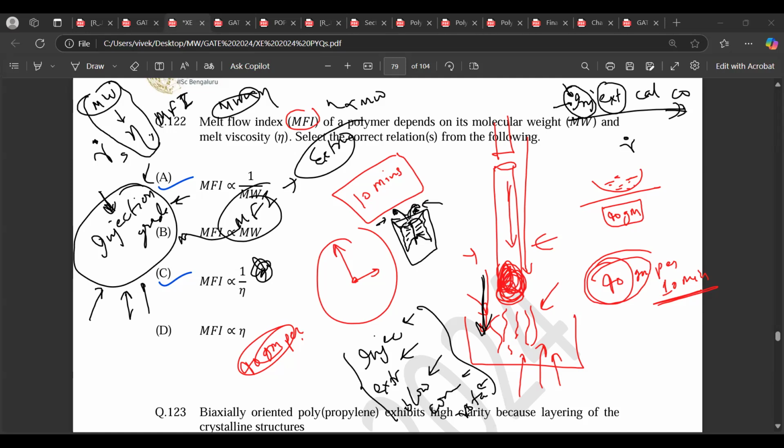What is the relation of shear rate and viscosity? Of course, we are assuming the polymer melt is Newtonian. What is the behavior? With shear rate, viscosity will be. Come on, guys, you have learned rheology. Tell me. Directly proportional? For Newtonian it's linear, viscosity doesn't change with the shear rate. Then you have one graph like this and one graph like this.